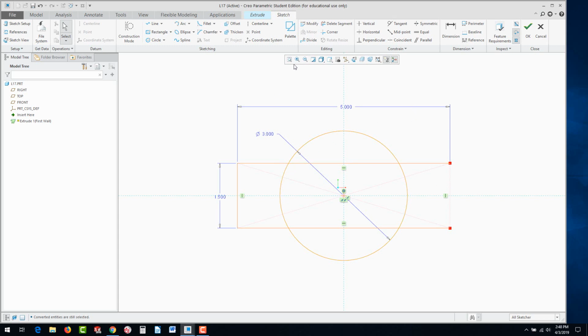Now for these, we want to trim these segments out on the inside. So go to Delete Segment, and you could just click on these edges here as you go around, or you could scribble through them. But be careful if you scribble through them. You could lose symmetry by scribbling through these construction lines. So avoid that. I would recommend avoiding it.